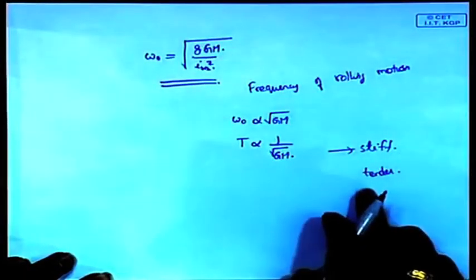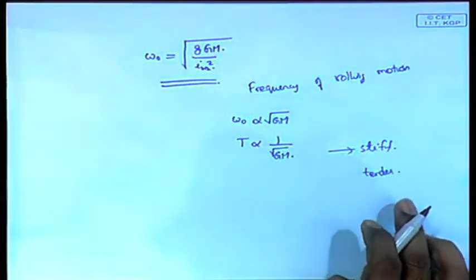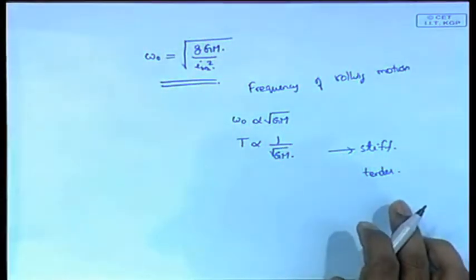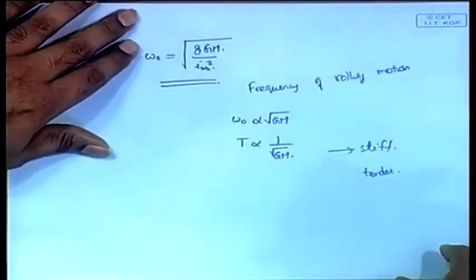But of course, that means you keep decreasing the GM, and that is also not very good, because from the stability point of view that might affect you. If you decrease GM to a very low value, that is a problem. So somewhere you have to do an optimization, some intermediate value you choose, where you have a value of GM such that both are okay: it's not too stiff, and it's not too unstable.